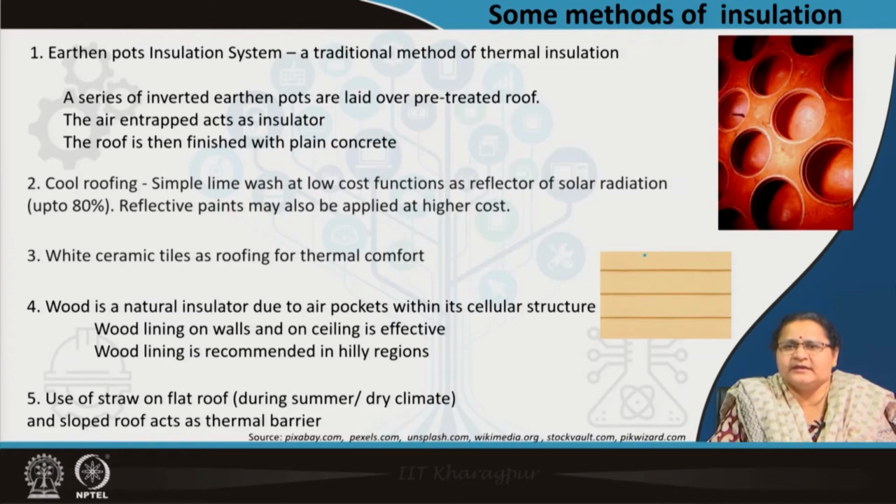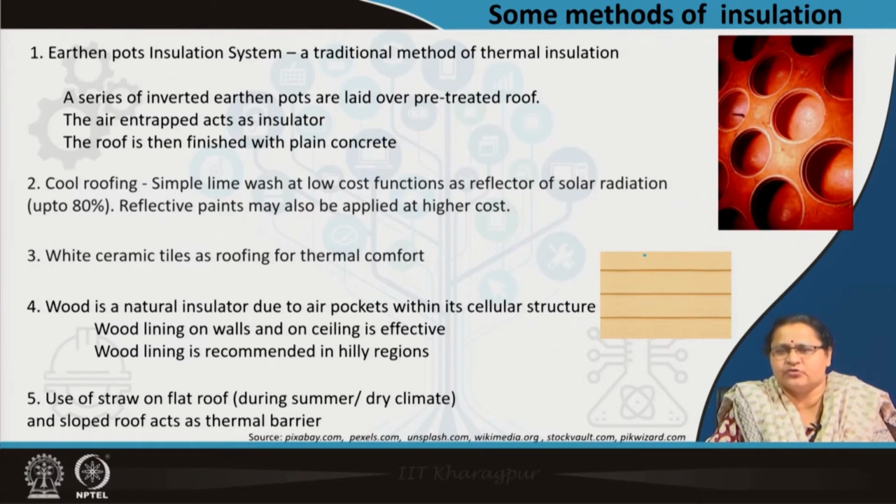So, what you see like tin roof or asbestos roof are really not the answer, because they trap a lot of thermal energy, but the cushion of straw is filled with air pockets. So, those are actually helping in the insulation. So, you have to keep your eyes open and find out what is the purpose of the material and why people have adopted it traditionally.